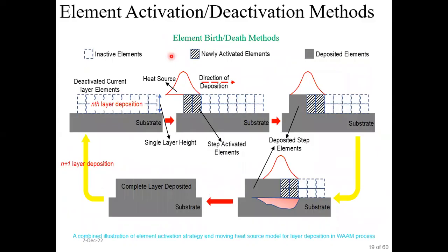As a second input, element activation and deactivation algorithms are important. As I have utilized Ansys APDL software, this algorithm is called the element birth and death approach in that software. This slide shows that approach.